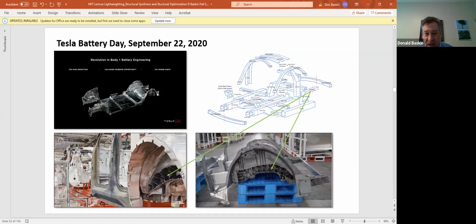So this casting takes up the rear part of the vehicle, the rear wheelhouses and the rear floor pan. And there are these webs that you can see in this picture here and here. This is the same part. That web right here is actually located at the side of the rear rail, like we discussed in body components and beams last time. So right in here.